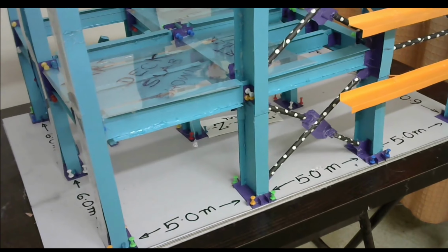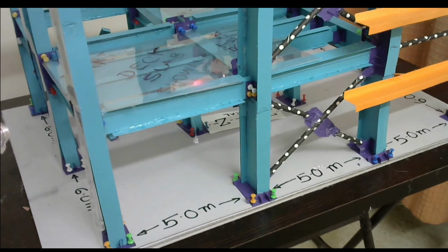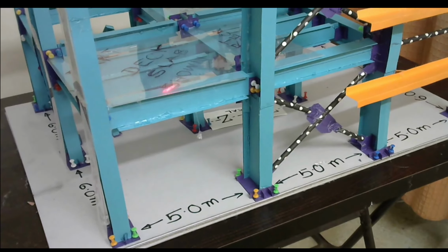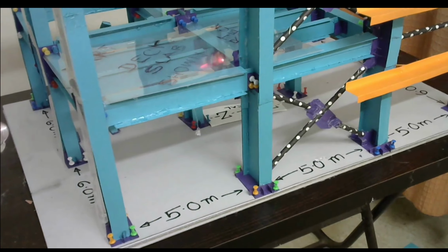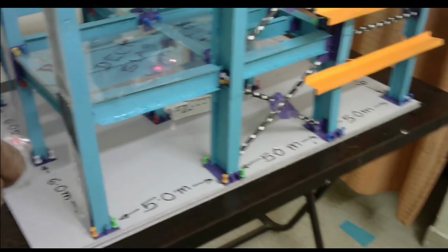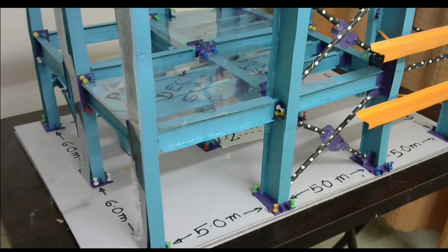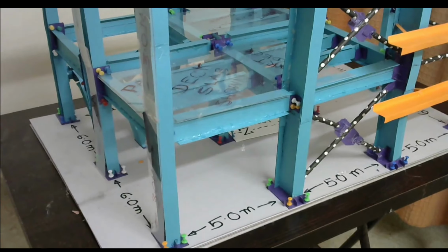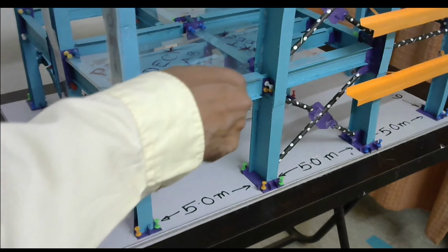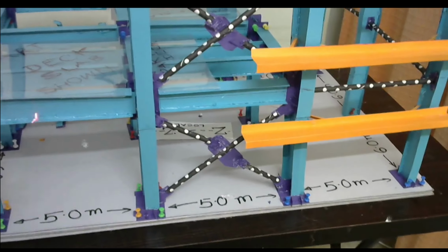If we consider a 130 mm corrugation to corrugation distance for a deck sheet, the distance LX and LY will be 130 into 2, 260 mm. But for all practical purposes, we consider one screw could be loosened, so it will be double of that. Usually the screw spacing is considered as 300 for various types of deck slabs. So 300 into 2 is 600 mm. So we consider LX and LY as 0.6 meter, and LZ will be 5 meters.